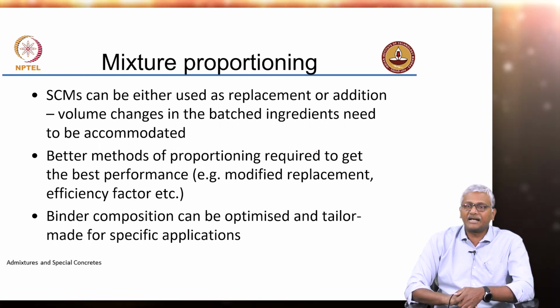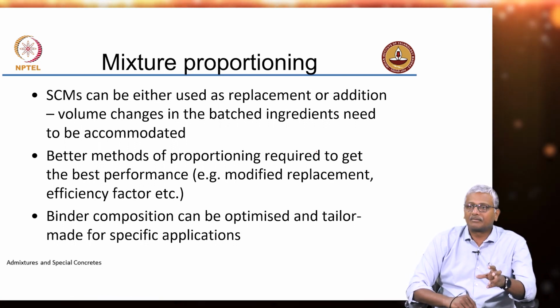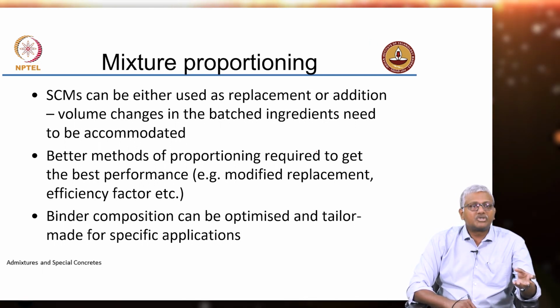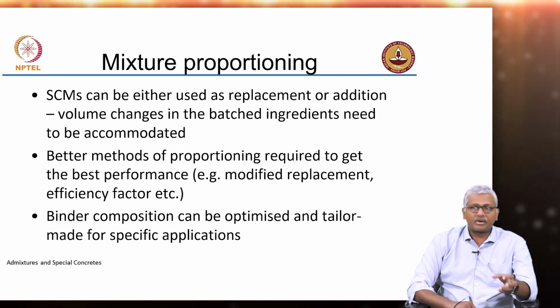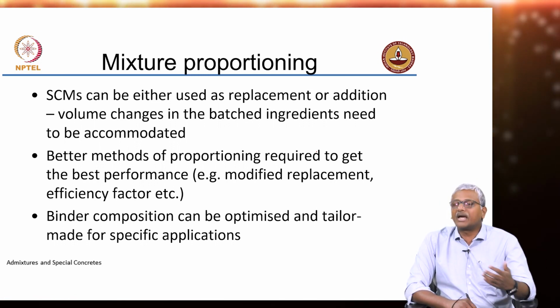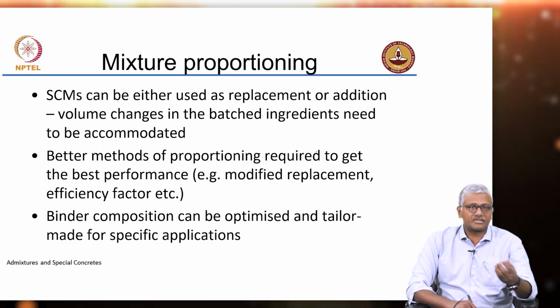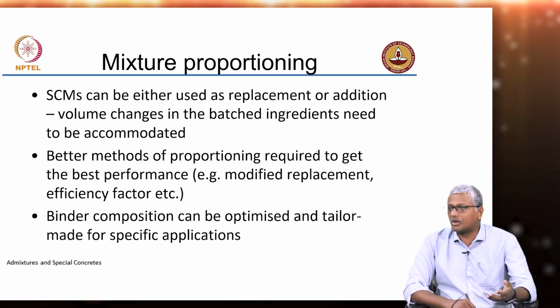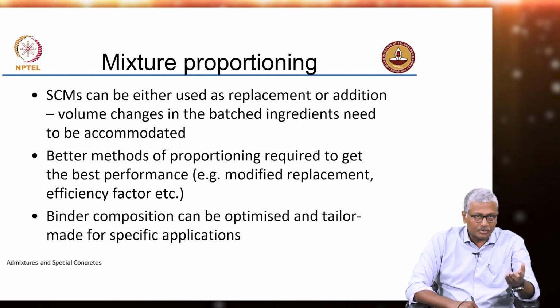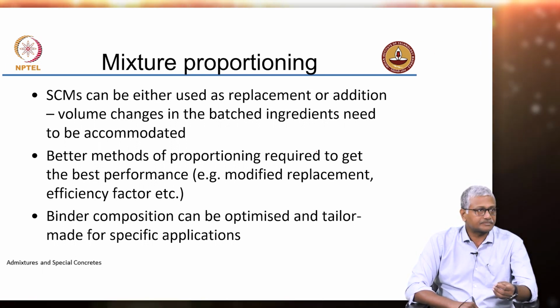It will not become practical to replace cement so much with silica fume or metakaolin. On the other hand, when we talk about slags, which are nearly of the same particle size as cement, right, which have a reactivity which is moderate and almost similar to cement but slightly slower, you can think about replacing much larger contents, also because slag is called a latent hydraulic material, right. Slag can react on its own with some activation.